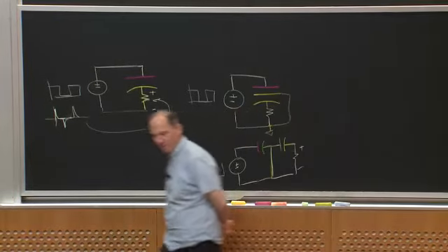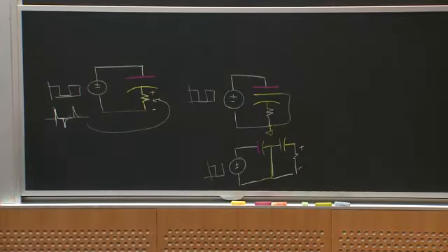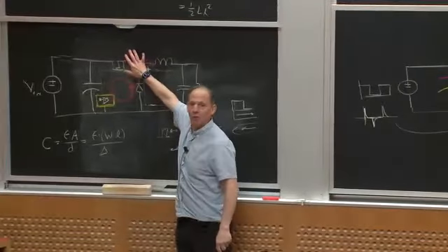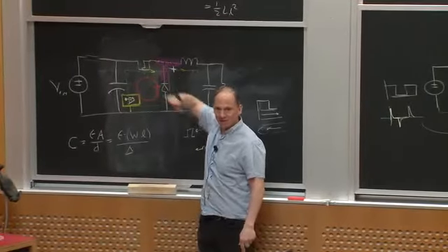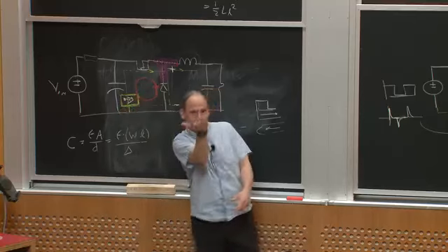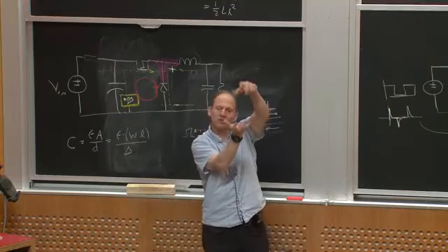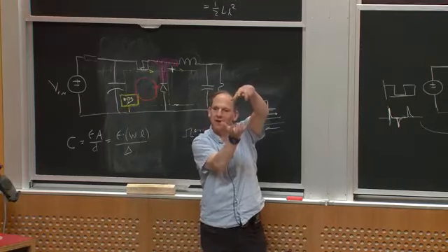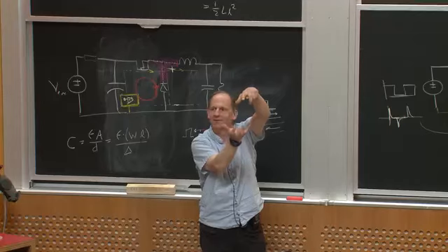Well, how would I do that? One way to do that is maybe I put this switching node on one side of my circuit board, I have a ground plane in between them, and I put my control circuitry on the other side of the circuit board to sort of shield it or hide it from the high switching node. Does that make sense to everybody?